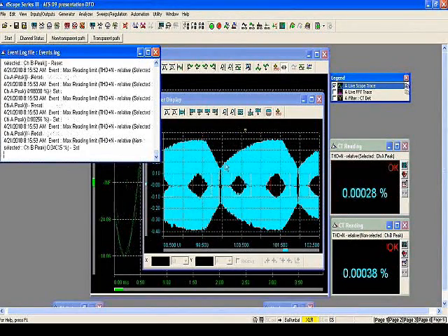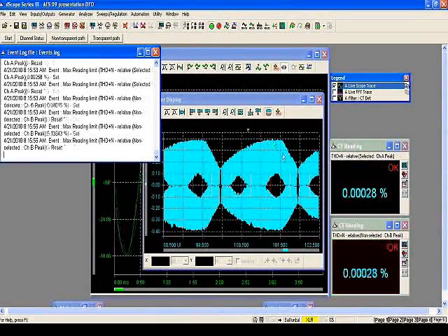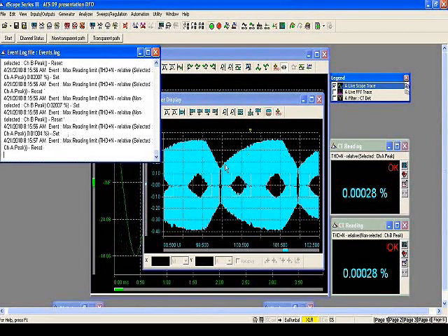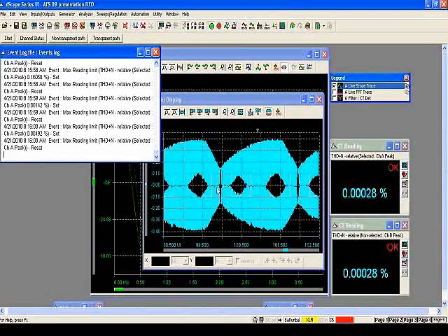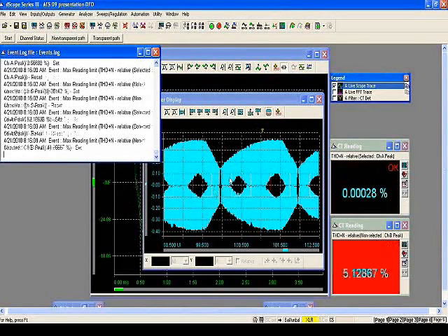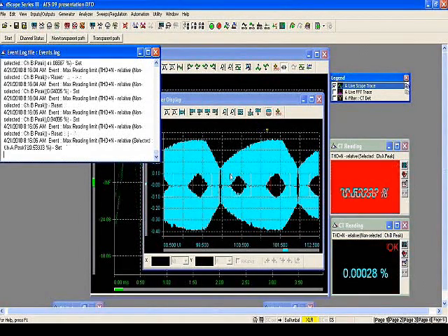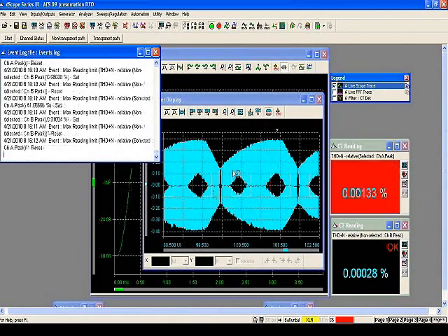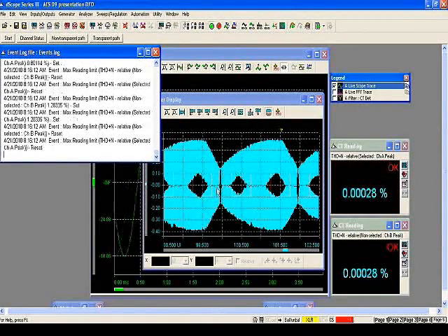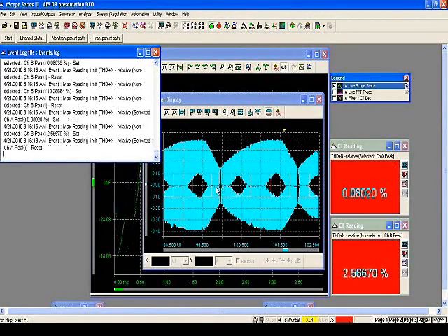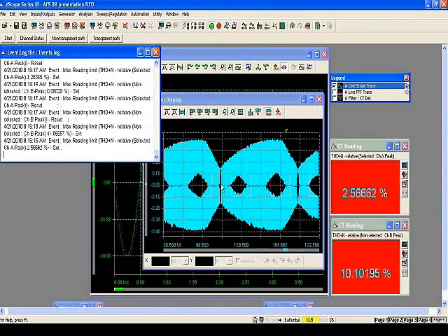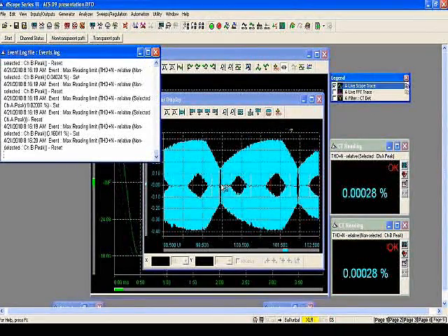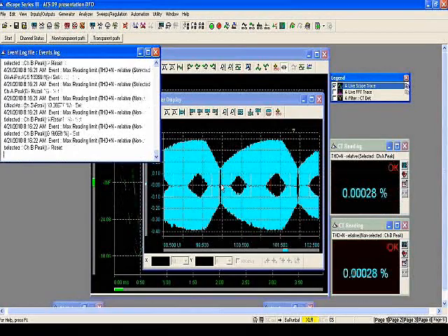We're seeing these very long rise and fall times. And these rise and fall times mean that the comparator and the signal, the pulse, is spending a lot of time around the zero cross. So any disturbance that happens during that time could possibly trigger this pop or glitch or even mute.